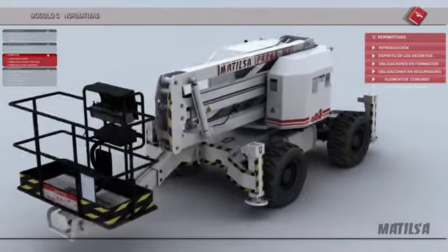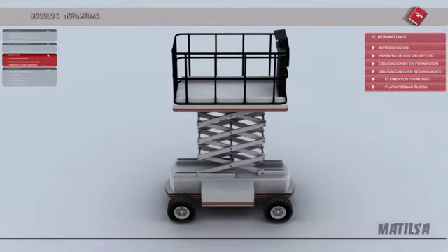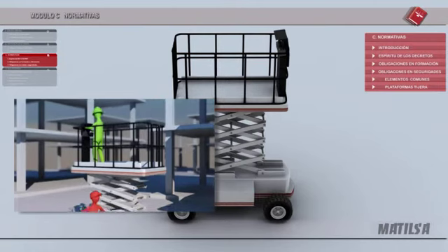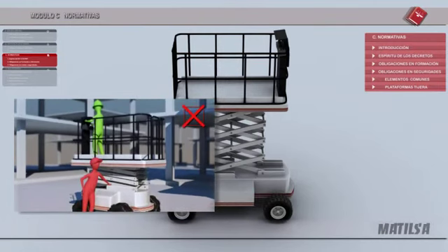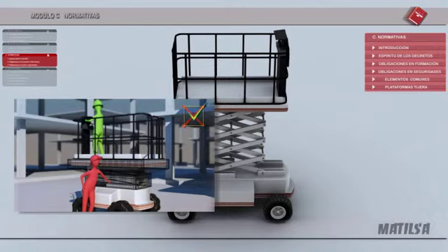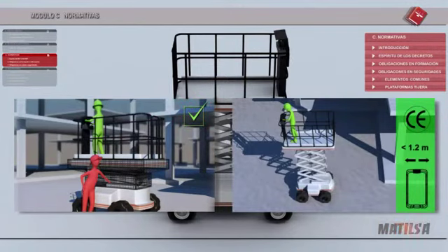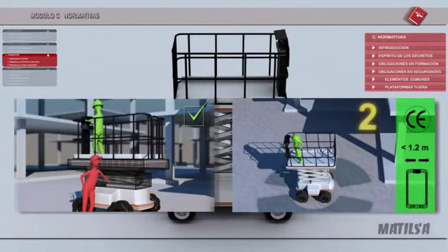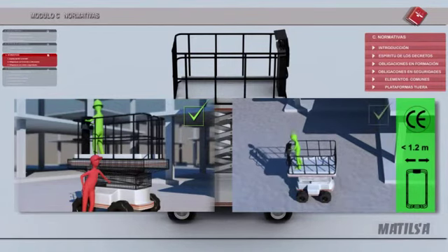Minimum safety measures that are only applied on the scissors-type platforms. Protection fences. The protection fences prevent cuttings or crushings with the scissor mechanism from occurring. For machines of less than 1.2 meters in width, the manufacturer may install an electrical device that stops the lowering about 50 centimeters before its final position and waits there for 3 seconds so that the worker can inspect both sides of the machine to check if there is somebody who might be hurt before getting off.